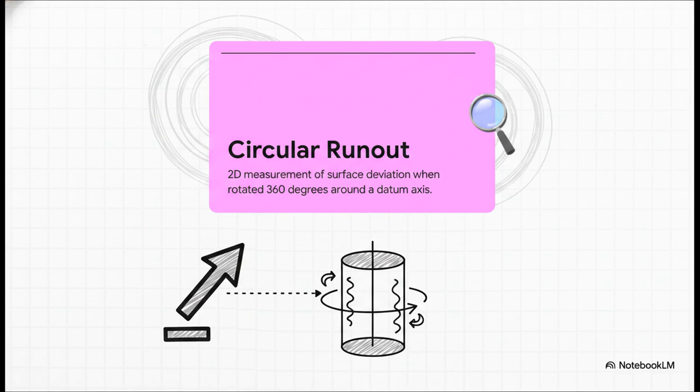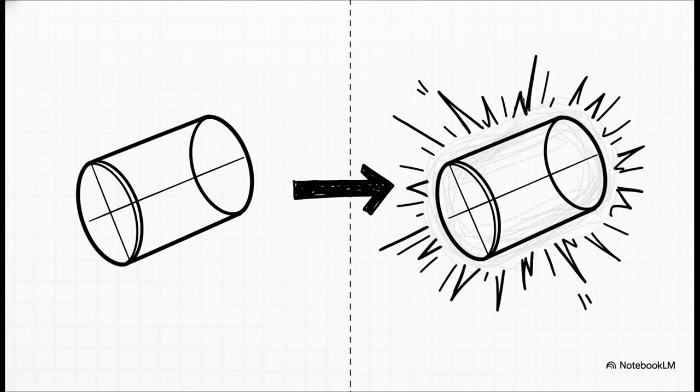Now, when you're looking at a machining print or an engineering drawing, you'll spot this tolerance control right away by its very distinct symbol, just a single arrow pointing diagonally upward. Whenever you see that arrow, you instantly know the designer is explicitly controlling how that feature behaves relative to a rotating axis. What's really interesting about this slide is how these controls directly impact the physical performance of rotating assemblies. These controls brilliantly bridge that massive gap between a static CAD model and real-world reality.